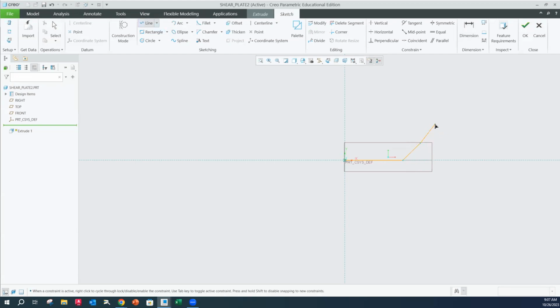Now, make sure that you are not adding any constraints. A constraint is going to be when I have these little lines or these little circles with these lines in them. I want to be an independent segment, and I don't want them in line with anything either, okay? So I'm going to click when there's none of those available. Then I'm going to go up here, and I'm going to add a third one to the mix. And then I'm going to double click, okay?